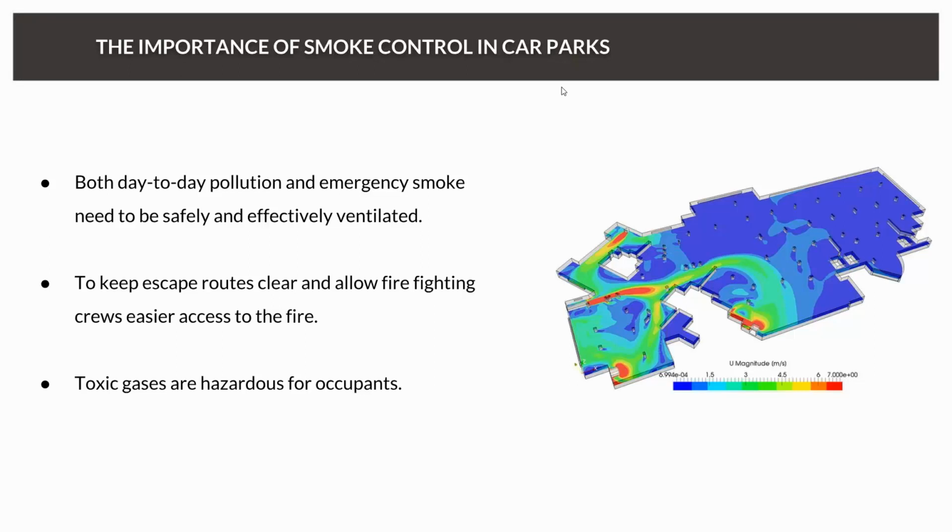And there, for example, we can use the CFD results also with other software to find the optimal escape path in the case of fire for different fire scenarios. And we can also simulate where toxic gases are hazardous for occupants and in which regions the risk is very high and that people can get injured through a high concentration of these toxic gases.